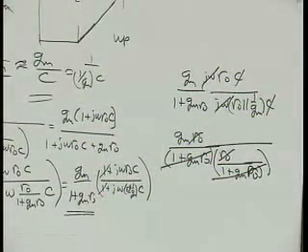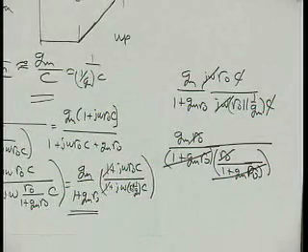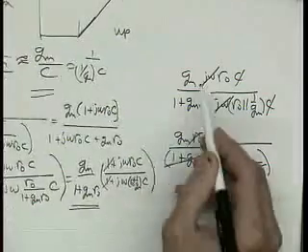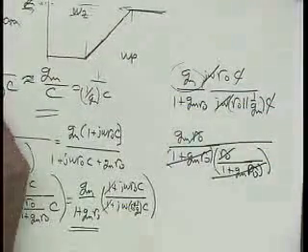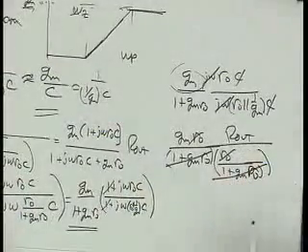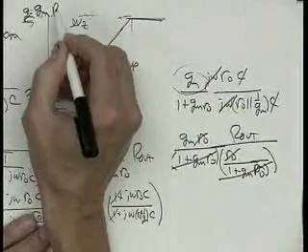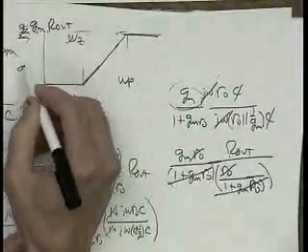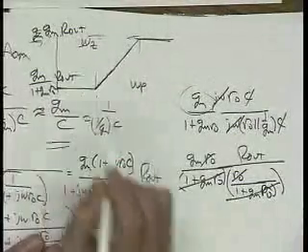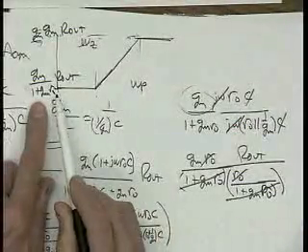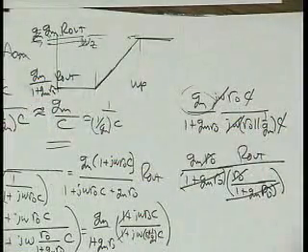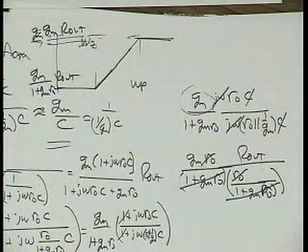This got the wrong units. This is gm or something like that. This is big Gm, big Gm common mode, right? So this should be times R out. So this thing goes up to Gm times R out, and it starts off as gm over 1 plus gm R0 times R out. So it starts out with a really low value, and then it goes up to be just Gm R out, which is actually the gain of the differential mode gain. So we have no common mode rejection at high frequency.